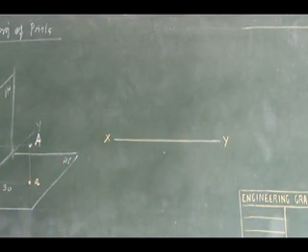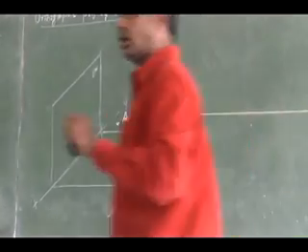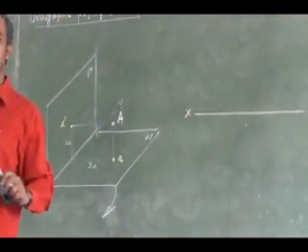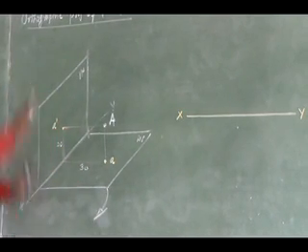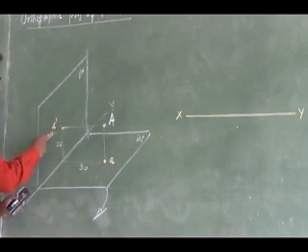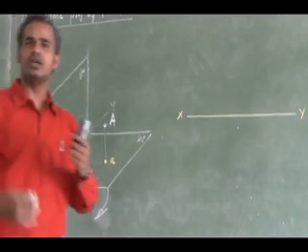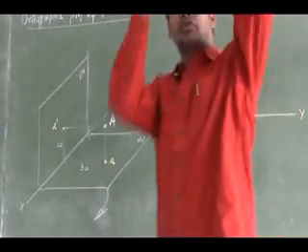You know the front view and top view. While I am rotating this horizontal plane, what should I do? To make it a planar shape, I have to rotate this horizontal plane 90° clockwise. Always I will be rotating the horizontal plane 90° clockwise, as in our setup we saw yesterday, right? So it is rotated 90° clockwise. Then I can say it is in a single planar shape. So a dash and a, that is front view and the top view, will be on the same line. That is nothing but a projector line of the point.